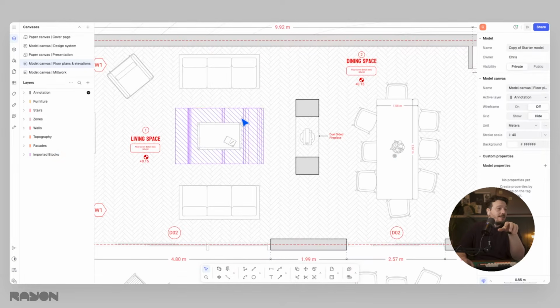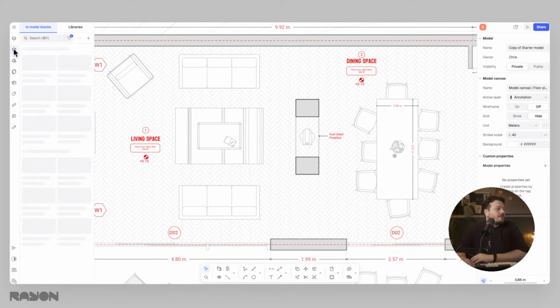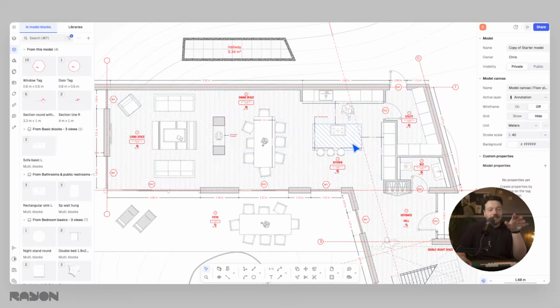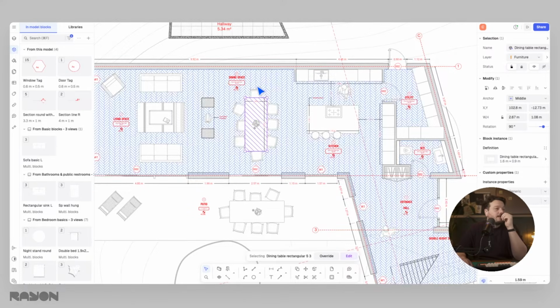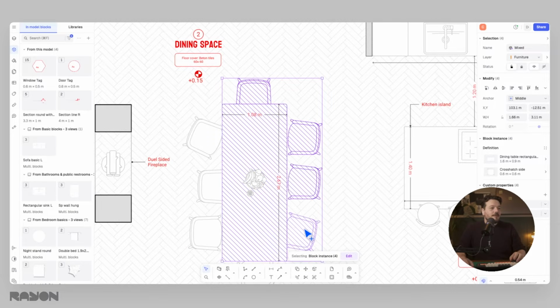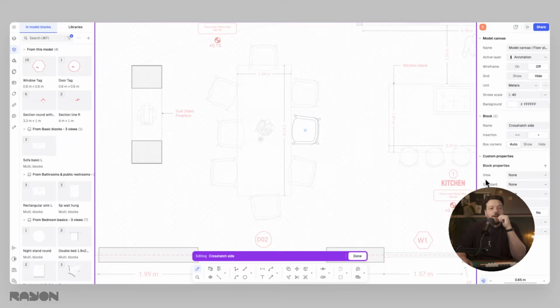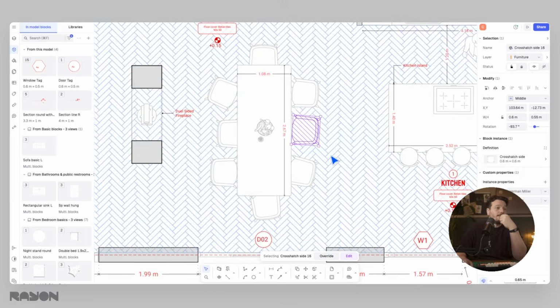And then within the floor plan, you can see these elements, which are our blocks. Now, I'll cover blocks a bit more in detail later, but in essence, we have our block library on the left-hand side. This contains all of our furniture elements, all the sort of features, things like the kitchens, even people, things like that. And they have front, side, and top views, so they're relevant for plan, section, elevation, and they all sit within the drawings, and I can move them about as I see fit. They again have a style, so I can go into this definition and I can look at the line style and the fill style, and I can change all of those as well.